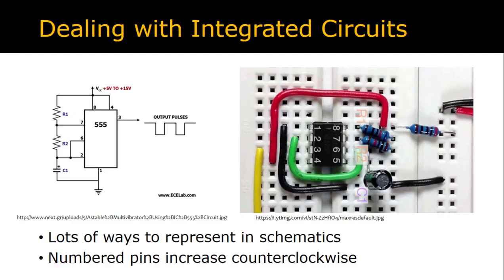One common use for breadboards is to attach integrated circuits to other elements in order to build electronic systems. Integrated circuits are devices which contain many smaller circuits that give them complex functionality. Integrated circuits interact with the world through many terminals. For instance, the integrated circuit shown on this slide has 8 terminals. Each of those terminals is attached to a piece of metal referred to as a pin. So I'll be using the terms terminal and pin interchangeably.